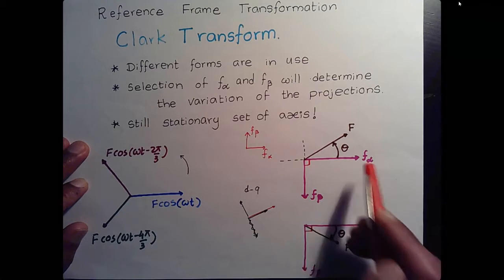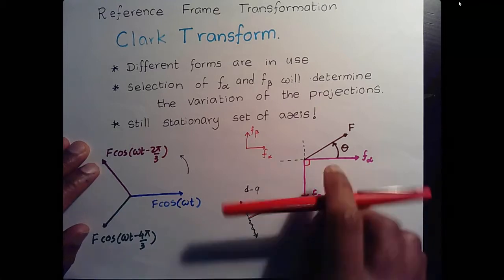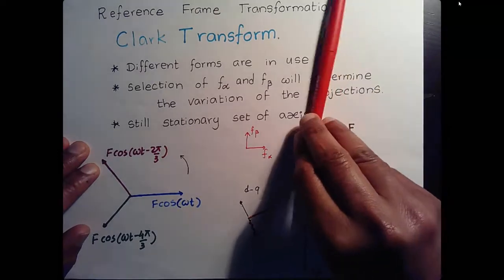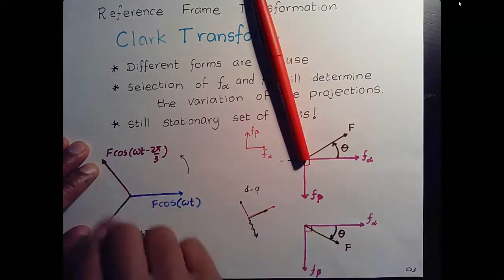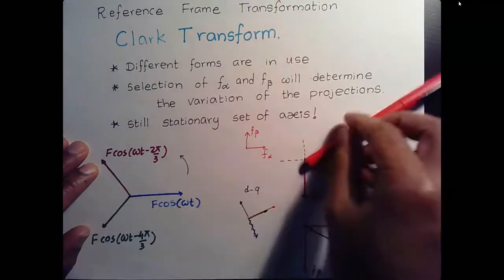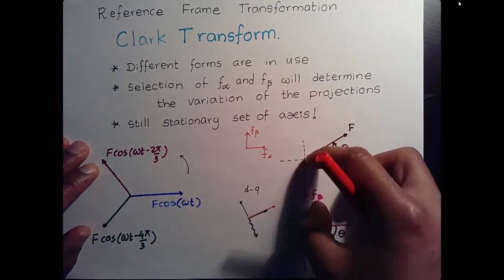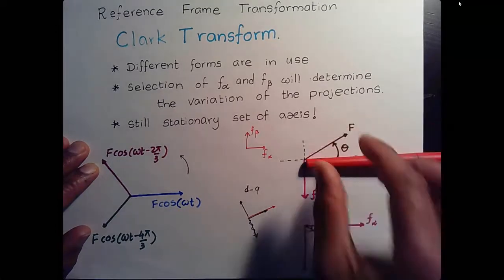They are not rotating. So what you are essentially looking at is, as the space vector rotates in the chosen direction, depending on how your phase sequence is set up, the projection on alpha and the projection on beta, meaning how those projections are varying.